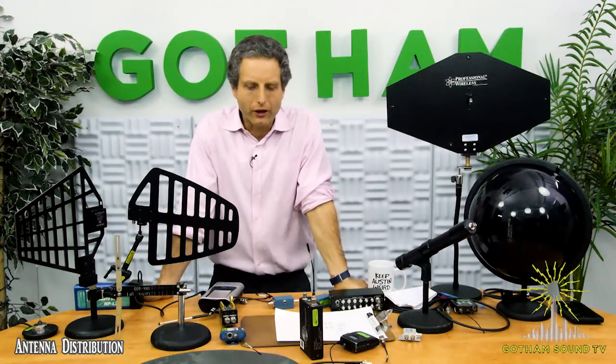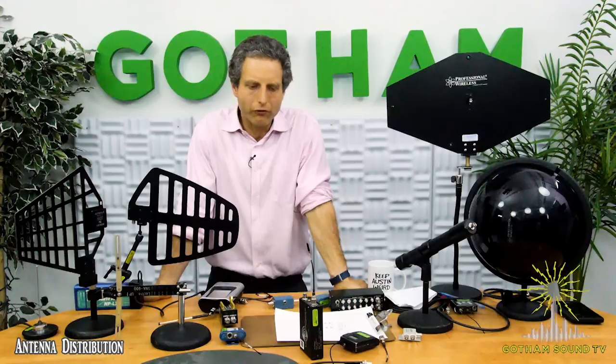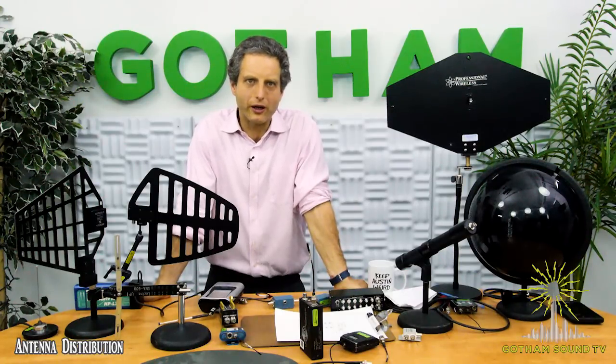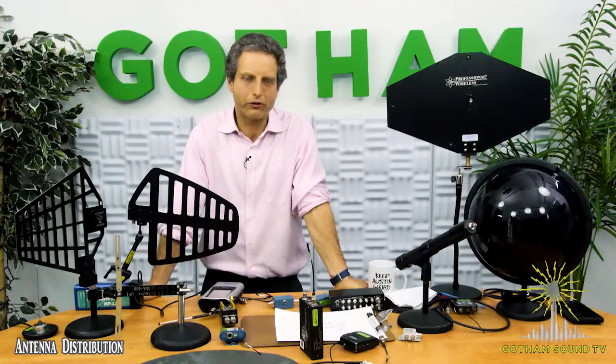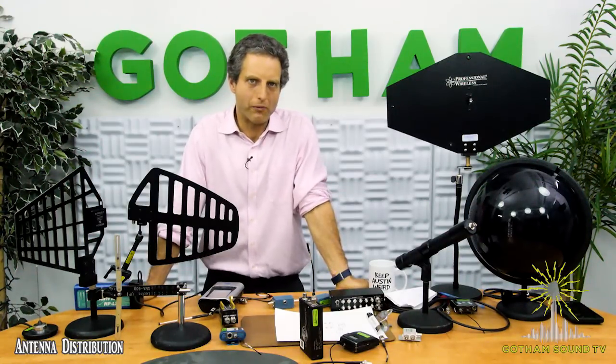Thank you, Jared. We don't want too much gain because too much gain, remember when I was describing the nature of RF amplifiers, it's not just the power of our desired signal that can make an RF amplifier go nonlinear. It's the nature of the undesired signal, which is also, aka the noise, that can make an RF amplifier go nonlinear.